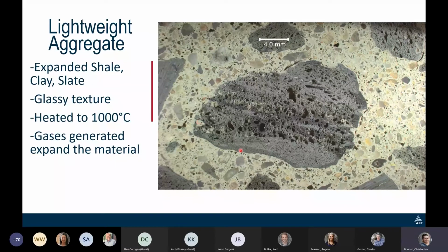So the way you do petrography on something like this is you can separate it based on shape, surface texture. Sometimes they develop a skin. You can kind of see what they're talking about here, like a little skin where it doesn't seem like it had too much of those gases generated on the outside. So surface texture, vesicularity, or finding incompletely expanded particles. Most of the time I've documented pyrite minerals in there too, that they can be concerned about. I'll show a really nice picture of why to be concerned about pyrite in a little bit.